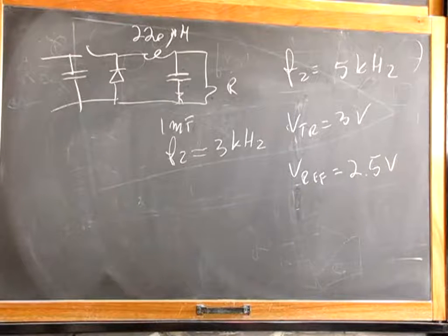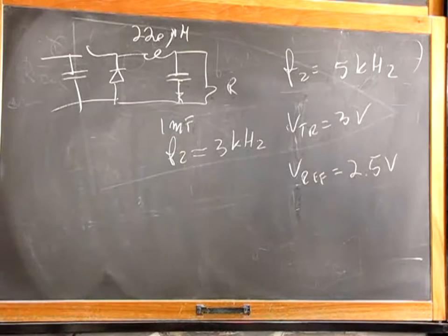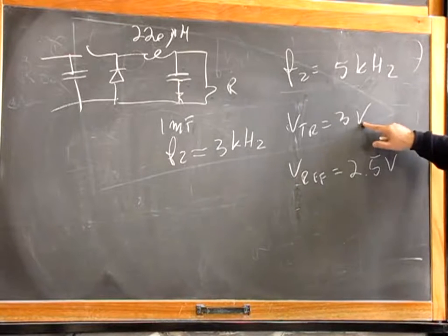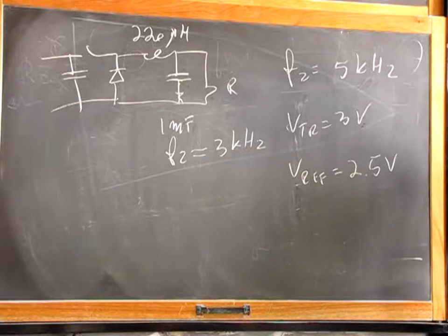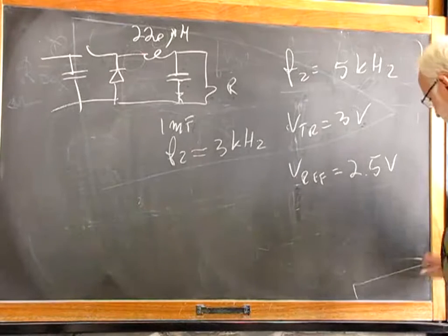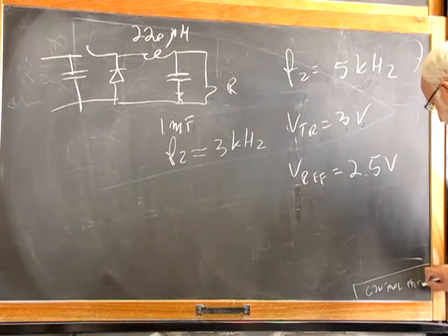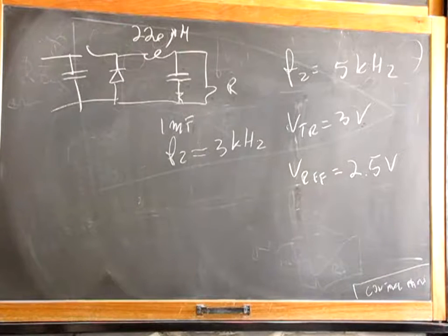Is the triangular without offset? We don't care whether there is an offset or not in V triangle. There is an offset, you can measure it with your scope. It's the sawtooth. But we don't care about it, because the type 3 compensator is integrating, so this offset is just reduced by the high DC gain of my compensator. Okay, 2.5, I think everything is there.